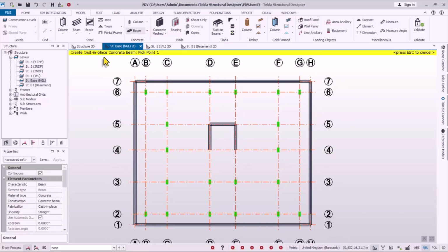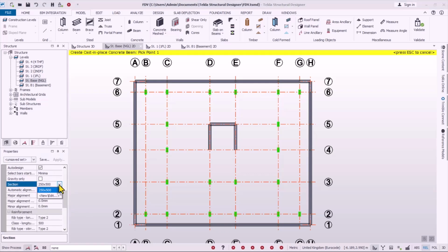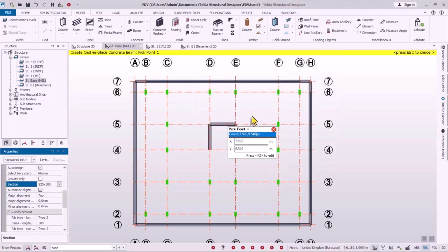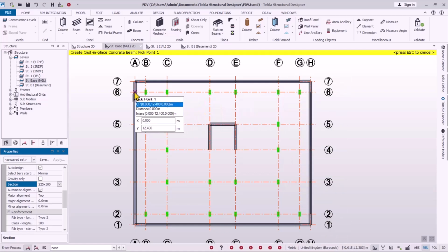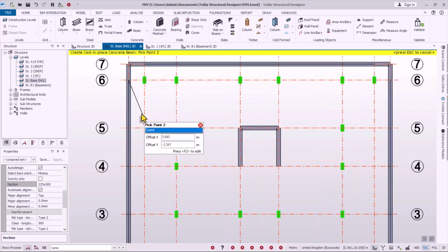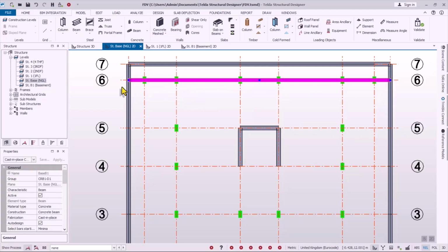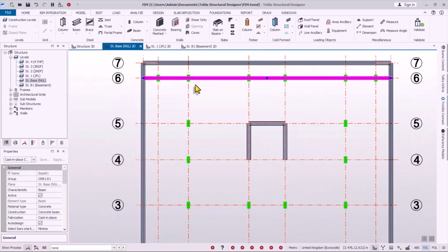So click on the beam right here. So we scroll down, see the materials and the beam properties. Let's check the sections. So we are going to be having 225 beams from here, 225 by 500. Click on the OK option. All right. So now we want to be creating a beam that will connect this point. So pick the first point. You can pick it all through to have it placed, but if you select it, you can see it is actually a single, continuous beam that is being placed successfully. All right, this is good.